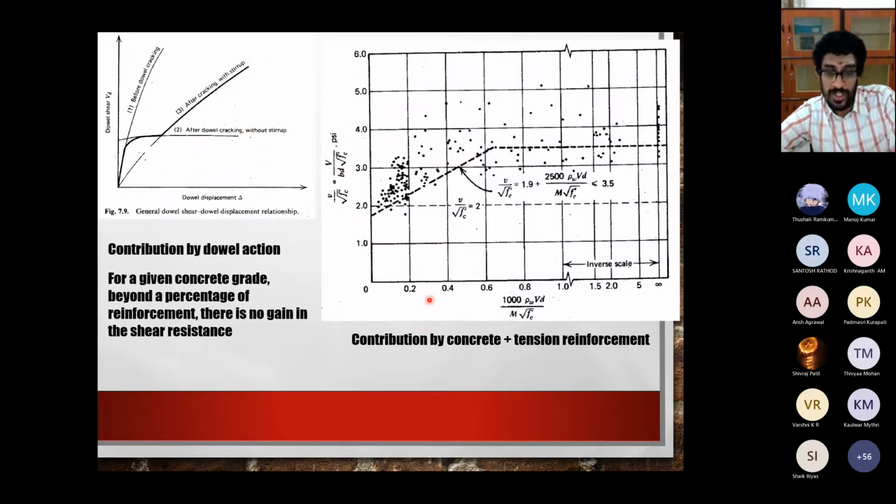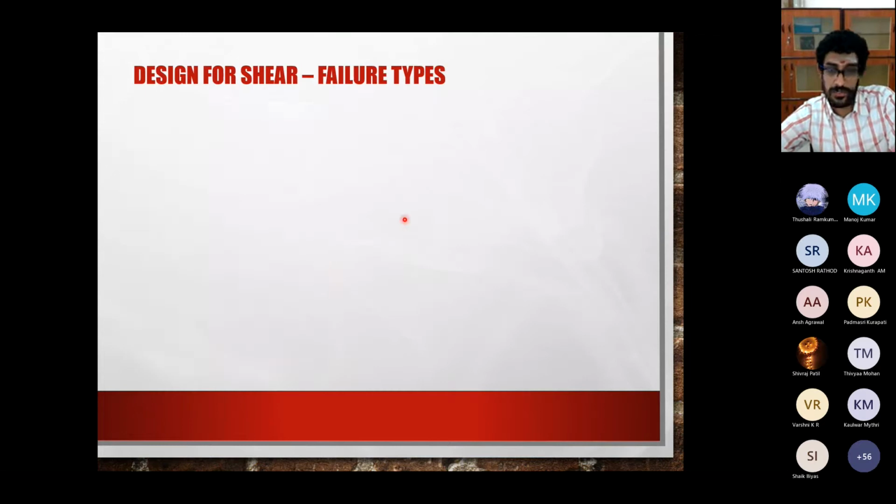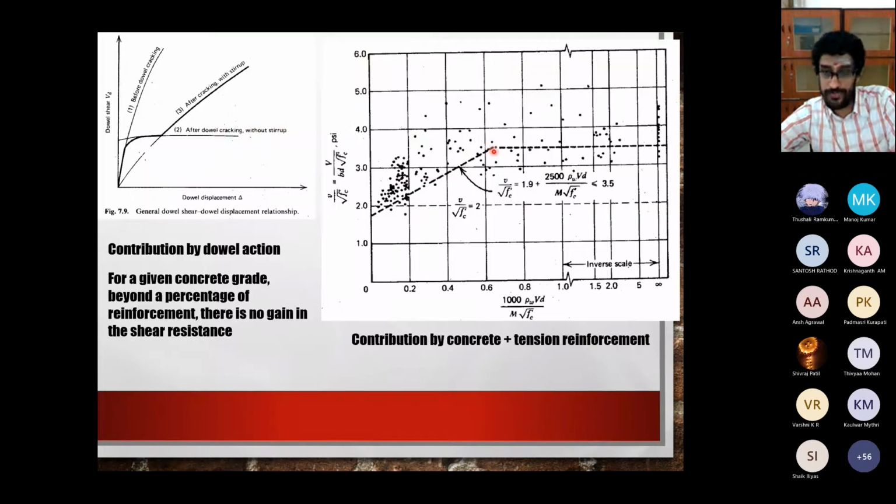Okay. So the reason is beyond this point. Beyond this point, remember that shear causes both. See, okay, what kind of stress causes cracking? Tension or compression? What type of stress causes cracking? Tension or compression? Tension. Tension. So when you have a shear state, that means it is a pair of tension and compression. Only then you have shear.